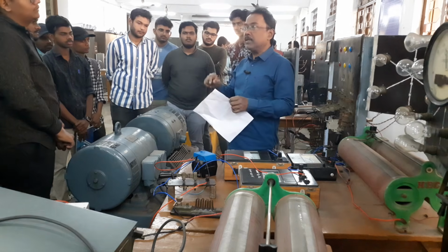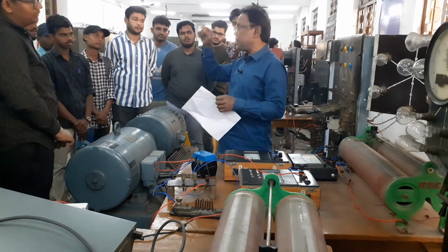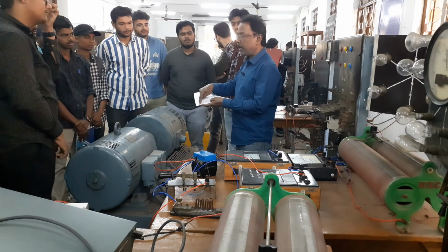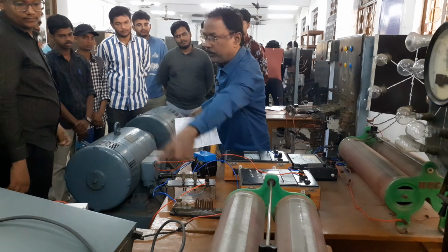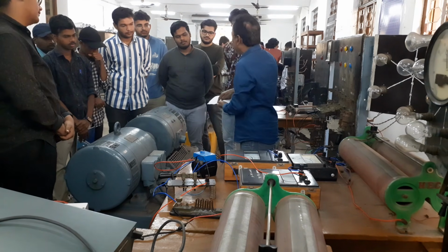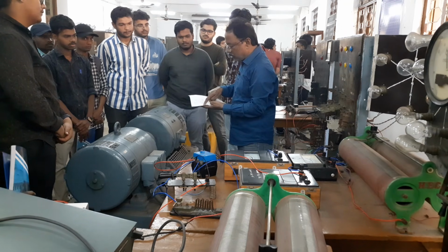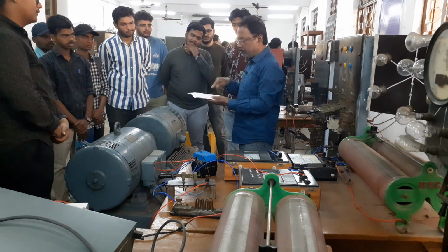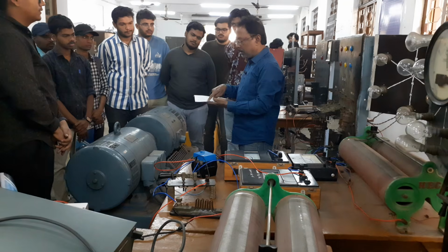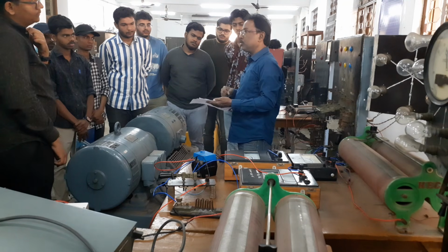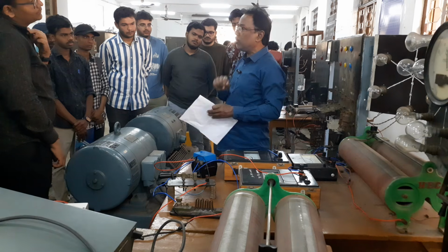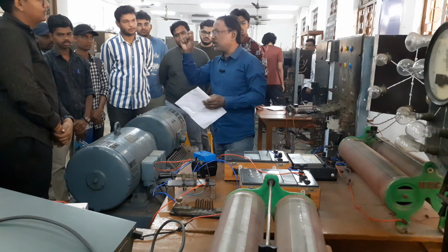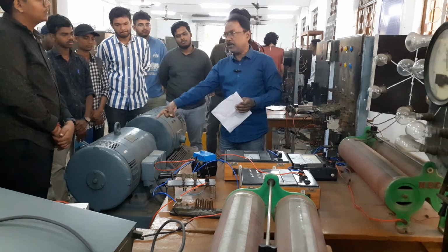At that time, we have to store that transient waveform. This is the storage oscilloscope. By using this probe, connected across the resistance in the star connection that is short circuited, we have to get the signal. A general oscilloscope cannot be used, because we have to short circuit for a moment only. For a very short span of time, because the three-phase alternator is running.